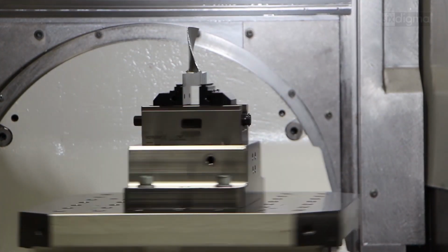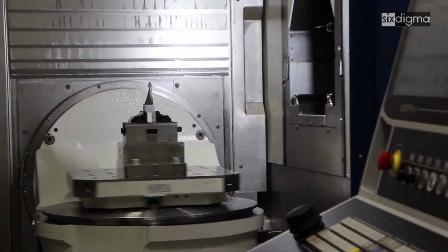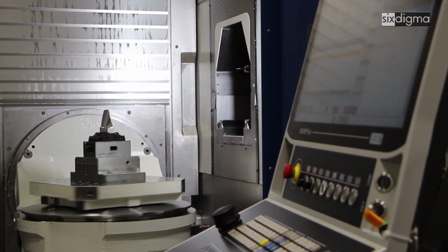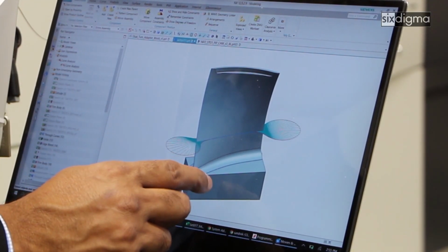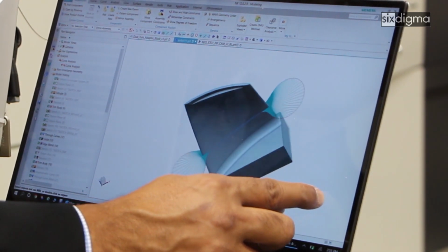Let's start with the simple airfoil milling toolpath. Small wiggles in airfoil surfaces often cause tiny variations in rotary axes of the CNC machine. Here we are looking at the curvature map of one of these cross-sections of this airfoil.